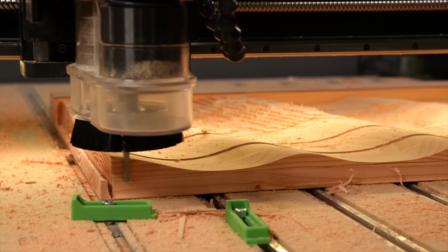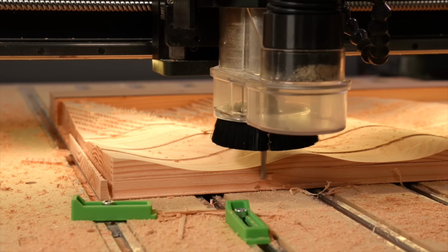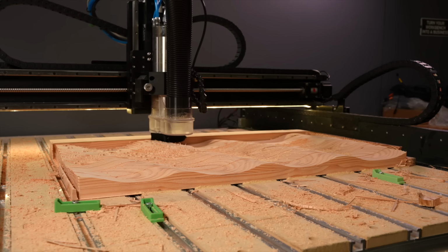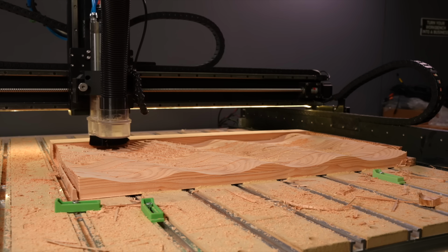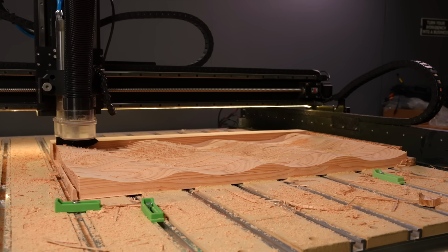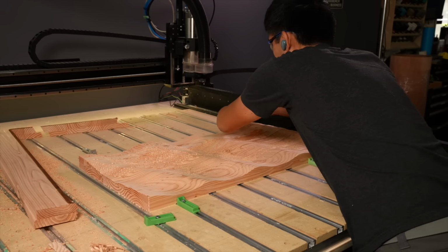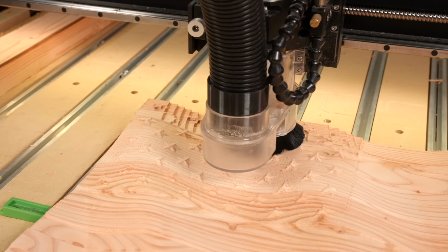You could do this cutout last, but if something went horribly wrong, like, oh, I don't know, I didn't use enough tape and the flag blank came flying off the table, I would much rather it happen sooner rather than later, after I'd invested hours and hours into machining the stars. As soon as the cutout was completed, I corralled my stock with clamps again and switched to my 1/8" ball nose end mill. Then I let the machine get to work on the stars.